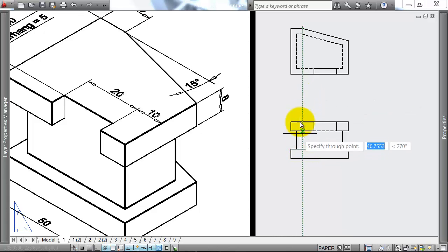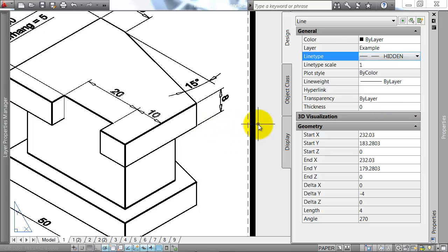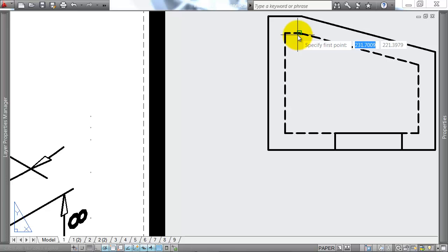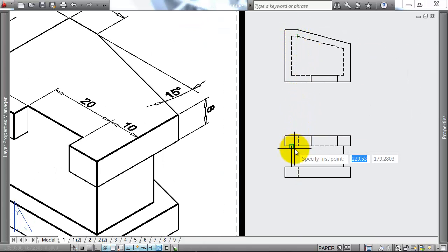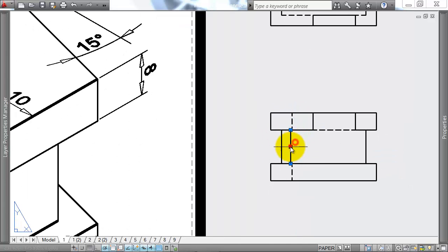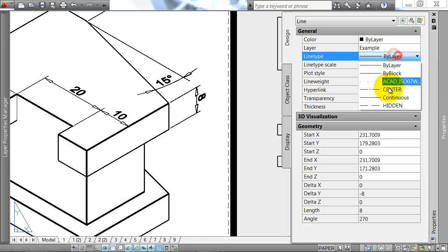So I'm going to have something along here, and I'm also going to have something along this hidden line corner. As for the corner at the top, that's a corner in the back of this top part of the shape. So I'll make that a hidden line. I'm able to copy that hidden line down here, because it's going to be not only in the top but the bottom. The top and bottom parts of this shape are the same, really. And then from the corner on here, this corner in there, that actually shows up as a hidden line in the center part of the shape. So it's in almost the same position, but not quite the same position as the hidden lines on the top and bottom of the shape.